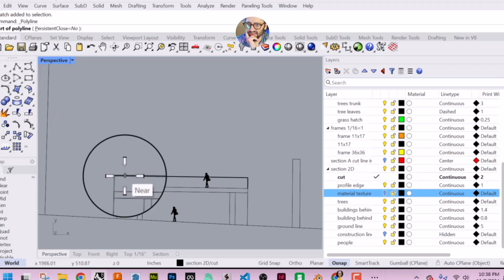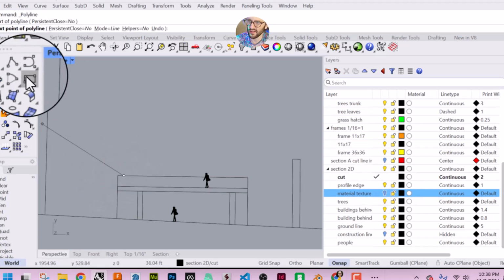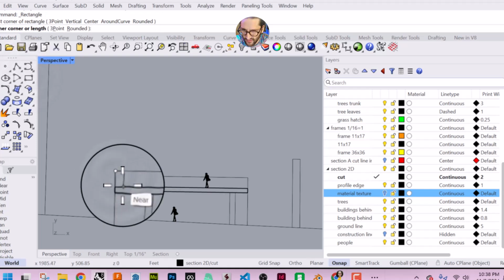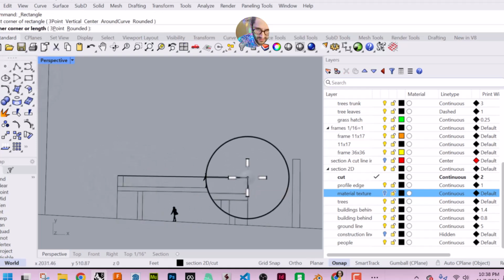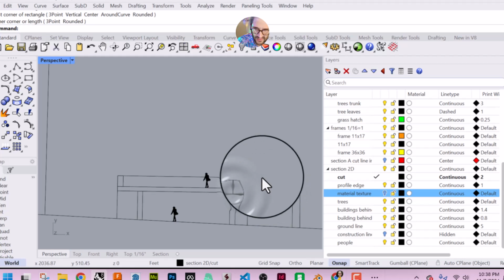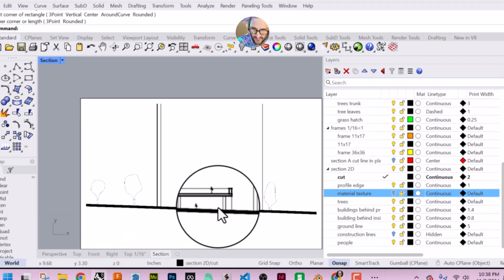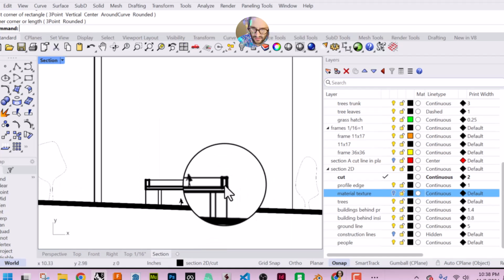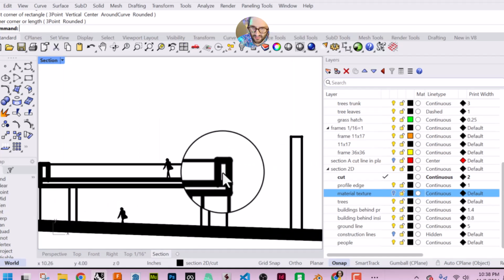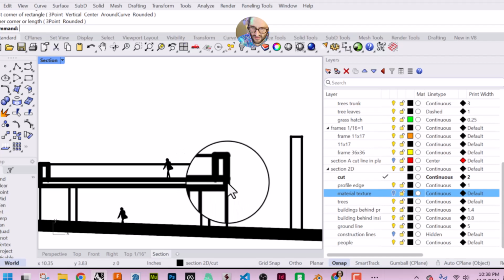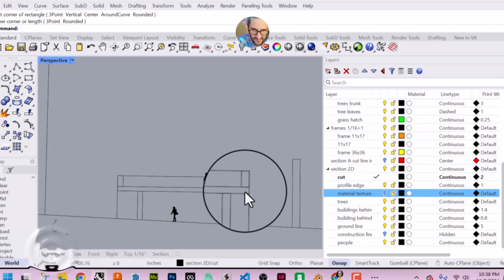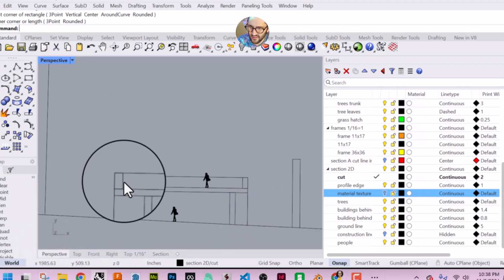If there's railings, I would see them here. So I can draw the cut on top of profile because it's thicker. And there we go. But I don't need a thick line in between these two cut things here. I should trim it.